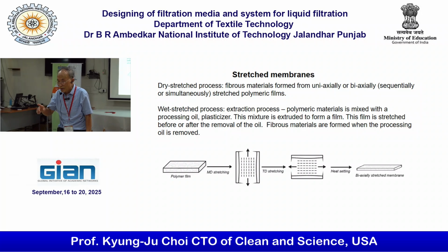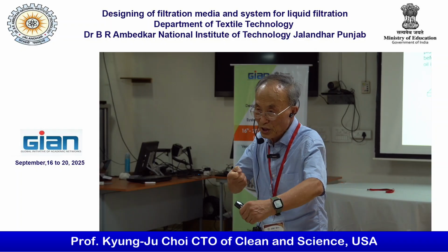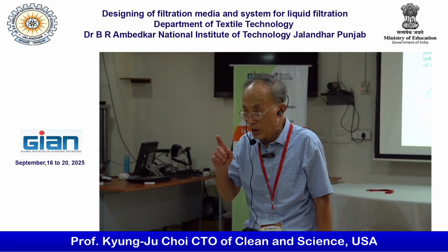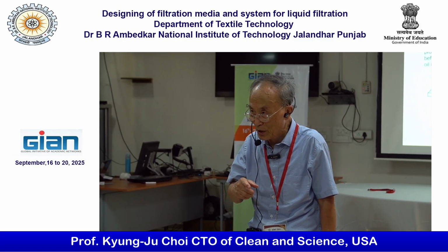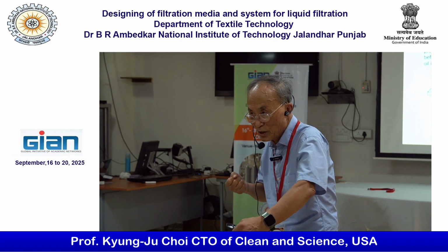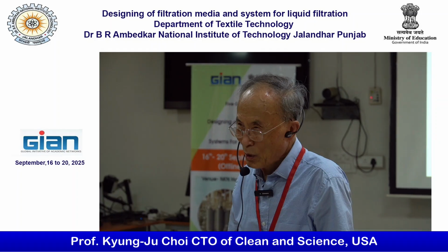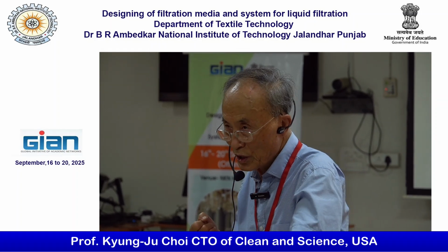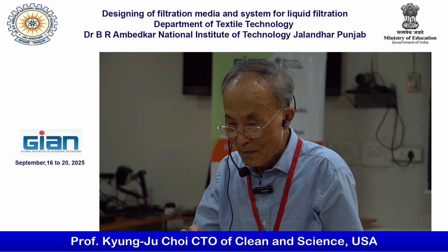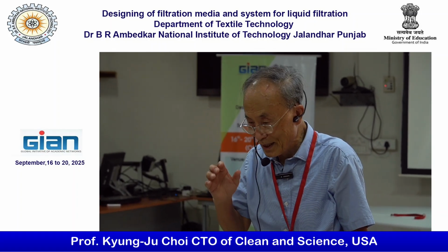The other important thing is, first you have to stretch in the machine direction only. We call it MDO, machine direction orienter. Normally, when you stretch in the machine direction, you have to apply heat. The temperature is quite sensitive.